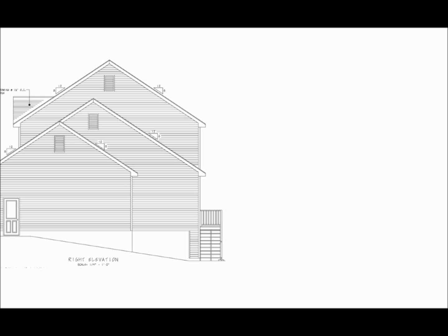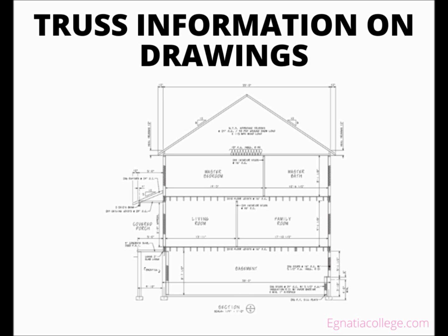Generally, the architect or designer who designs the house has some idea of what size and type of trusses will be required. The plans and elevations for the building show a lot of information about the trusses. The pitch of the roof can be seen in the building elevations. Section views through the building show trusses, but the truss shown in a section might not be the truss the engineer designs. Notice that a note in the truss area in this figure says the city and PE, which stands for Professional Engineer, approved roof trusses at 24 inches OC and gives load information that the truss designer will need.